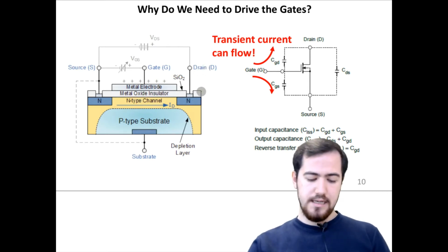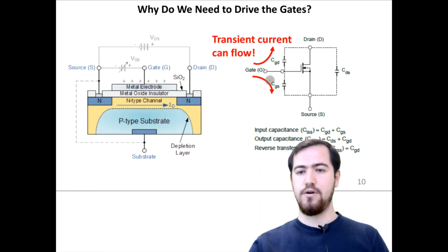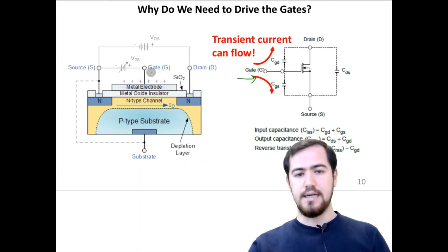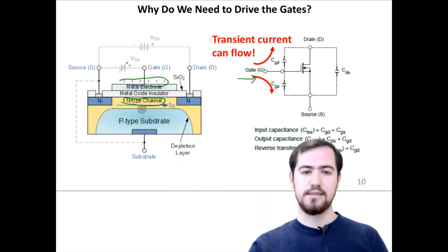We were told that the gate of the MOSFETs includes a capacitance, which results in no current flow through the gate pin. However, this is not valid for the actual case. When we provide some gate bias voltage between the gate and source, we accumulate positive charge on the gate pin, which results in accumulation of free electrons on the channel. By this method, we turn on this MOSFET or the IGBT to conduct some current.